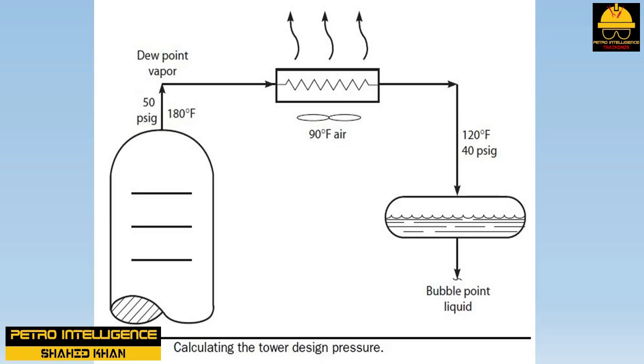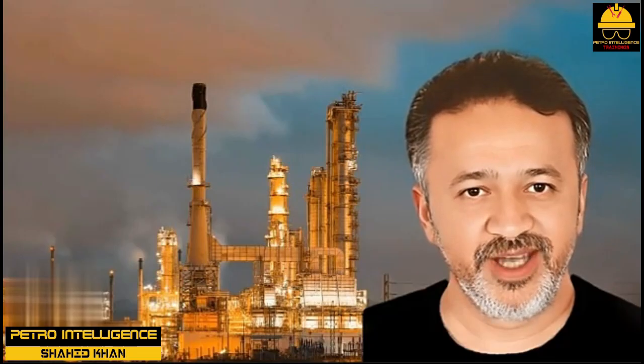A simple distillation tower, like that shown in the picture, also must obey its own phase rule. Here, because the distillation tower is a more complex system than the reflux drum, there are three independent variables that must be specified. The operator can choose from a large number of variables, but must select no more than three from the following list.